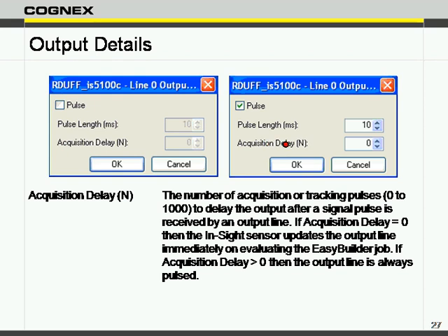Another functionality we have to offer is our acquisition delay. You can use the acquisition delay if your camera is looking at a product in a machine, the product is in there, and of course your reject station is two or three stations down. What you can do is say, I won't output that failed job result until three acquisitions later. And that is our acquisition delay functionality.